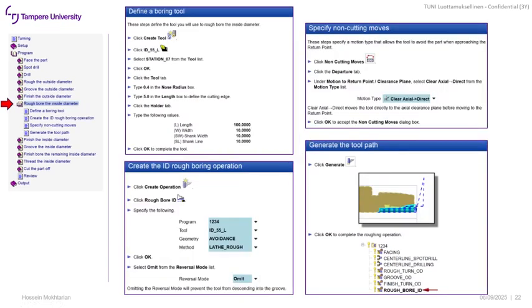So next would be defining the rough bore of an inside. So here we need to define the internal tool on another station. So we can see I was trying to define the internal tool for an odd number. So for example, maybe number 6 or number 8 if it is available in my turret. Then here we're just specifying a different type of holder.